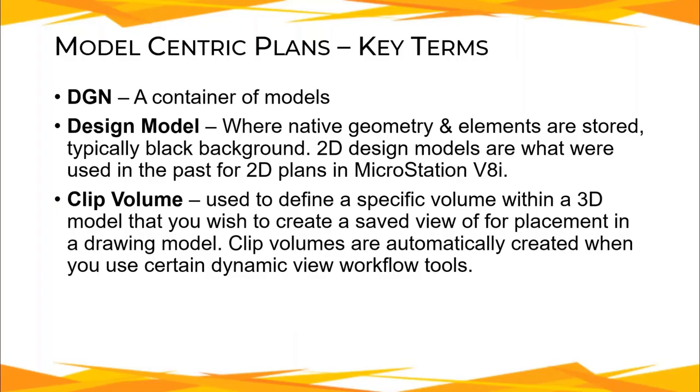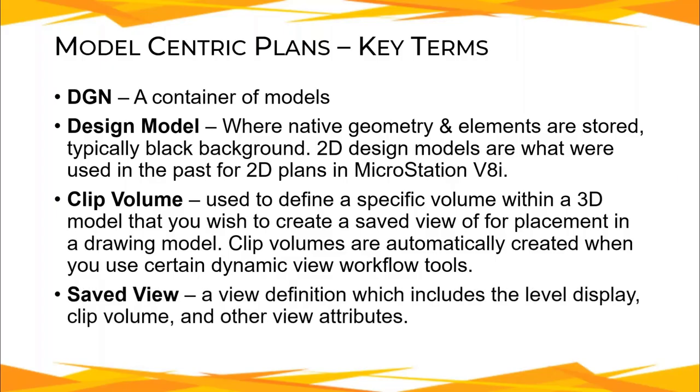Clip volume, this is used to define a specific volume within the 3D model that you wish to create a saved view of for placement into a drawing model. Clip volumes are automatically created when you use certain dynamic view workflow tools like the section callout tool or a couple other ones. It's just used to define the region of the 3D model where you want to actually show a 2D view of. Saved view, this is a view definition which includes level display, the clip volume, and other view attributes.